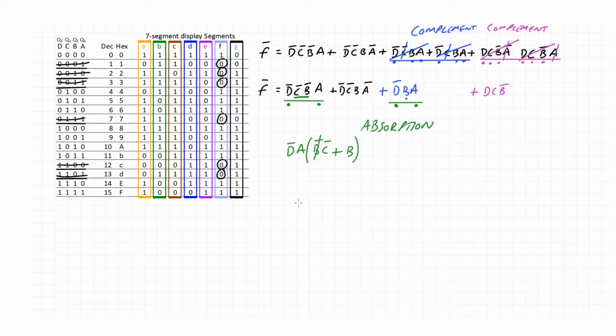So it's the not B that we need to get rid of, because that's the complement in the ANDed term. Then multiply out. Not D, not C, A. I'm just doing it alphabetically if you don't have to. Then not D, B, A. You notice with the absorption law, it's only one of the terms that actually changes, but I still write them out again afterwards to show what I've done.